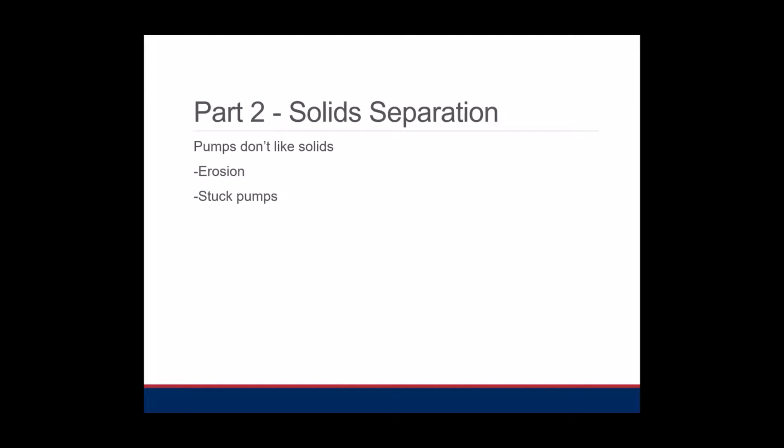Essentially all those solids, sand, and formation fines that were being produced up the wellbore basically shut down and fell to the bottom. If they're in the tubing, they fall on top of the pump. And if we have a stuck pump, we can have a rod part. It causes quite a bit of issue. So the second part, combined in production, is solids.